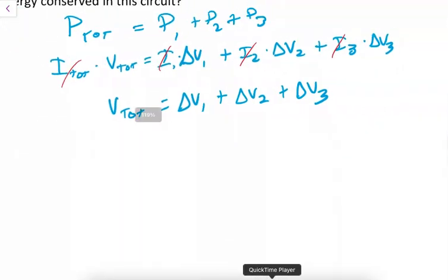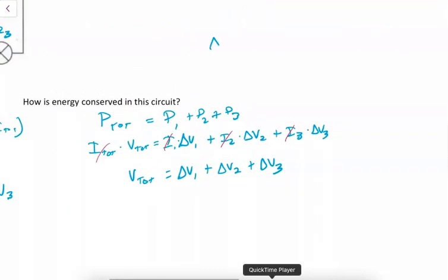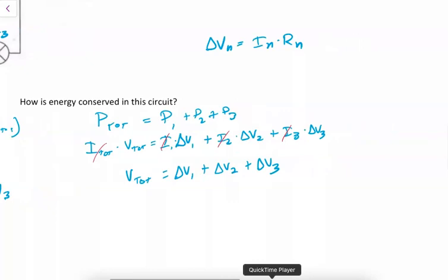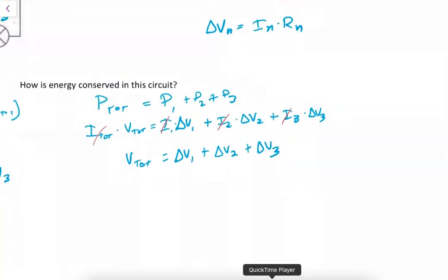That just means that the total potential difference available by the battery is distributed amongst the resistances. So each resistor gets a voltage. And then we also said, how much did that voltage matter? From above, this is equal to IN times RN. But IN is constant. I1, I2, I3 is equal to I. So let's plug this in: I times R total, because it's V total, right?